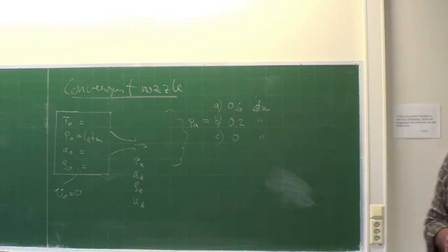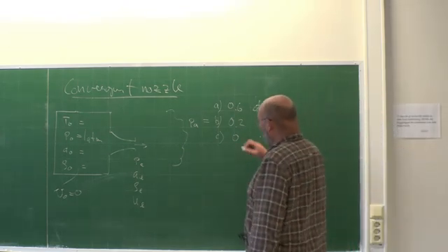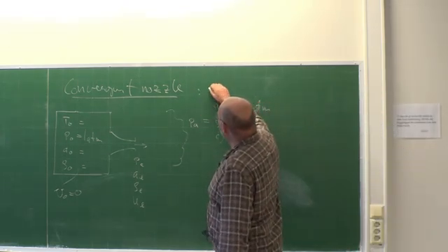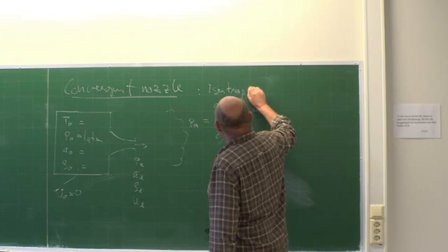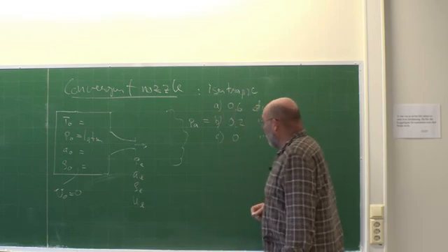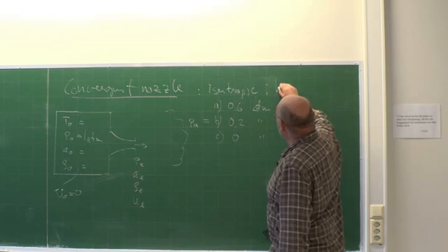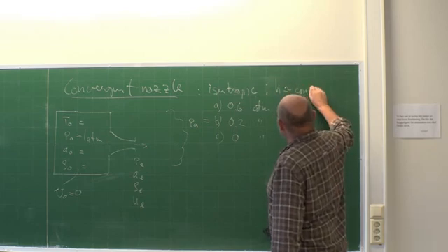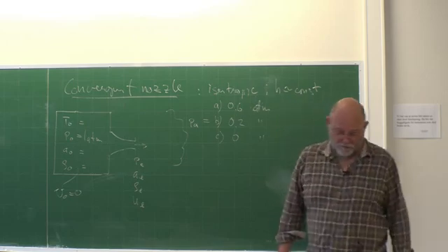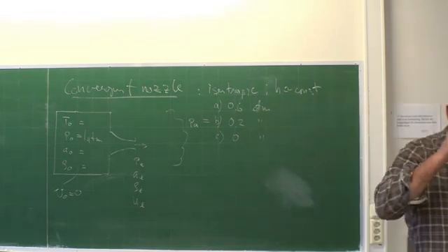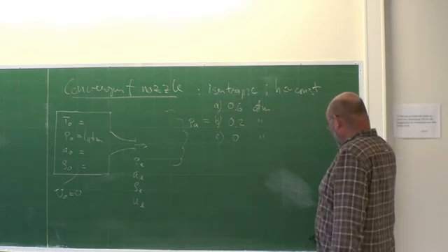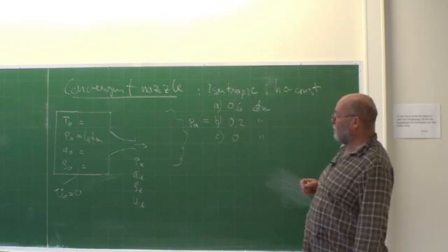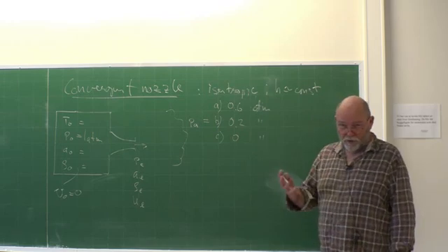And now you can start calculating if we do the following. It's isentropic. So the enthalpy is constant. It's a cheat. Yeah, we know that. It's not correct, but more or less not too far away. So it's adiabatic and it's reversible.